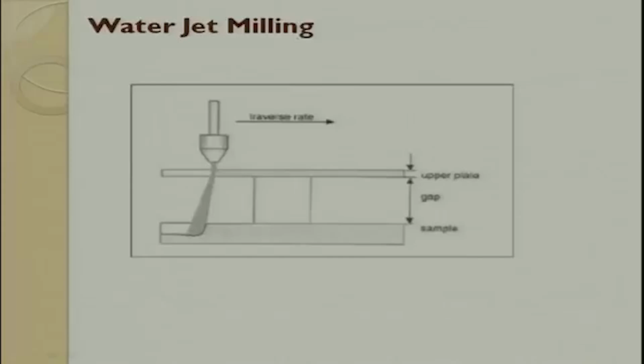For example, when we use laser or when we use milling operation, the thermoplastics expand and contract to give the output. So, the water jet can be used for milling. Milling is basically what we are trying to talk about, to make pockets. Till now what we were seeing is only cutting, and cutting means through-to-through cutting. Now, what we are trying to talk about is how do you mill a surface to get the required output.